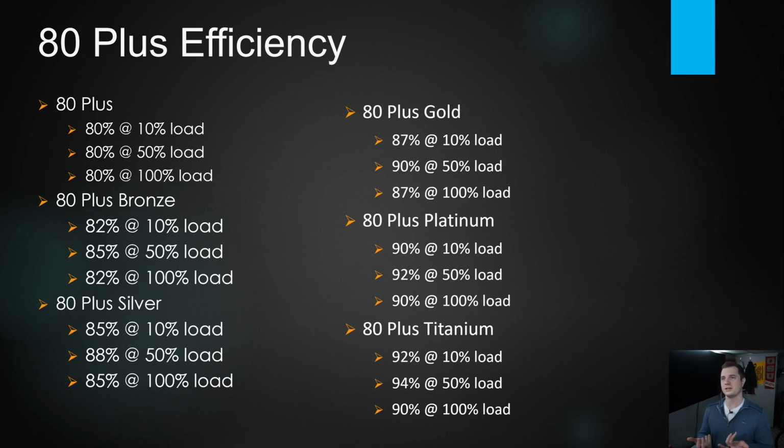Talking about efficiency now for power supplies, 80 Plus is a standard. And here are your metrics for that standard. If something is 80 Plus Titanium, and they've actually been certified, here is the minimum specification down at the bottom right. So again, this is one of those things where you don't memorize it, you Google it. Just know that there are a handful of 80 Plus certifications, and you need to know that they exist. So when you run across Platinum or Titanium and you don't know what that is, go find it. All right.